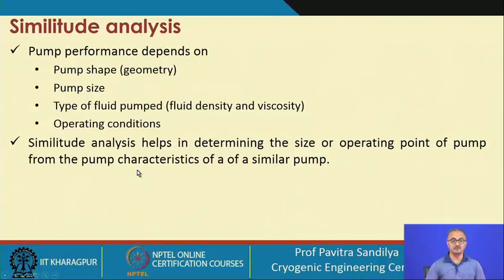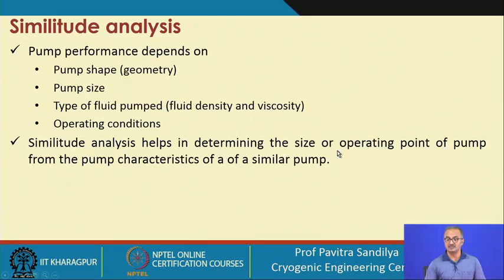Now, we come to something called the similitude analysis. In this, I shall not be doing the detailed derivation, which you can find in the books and other subjects. Here we shall see why we need it. The pump performance depends on the pump shape, the geometry or size, the type of fluid being pumped, that is the viscosity and density of the liquid, and the operating conditions, that is the temperature, pressure, etc. Now, this similitude analysis helps in determining the size or operating point of the pump from the pump characteristics of a similar pump.